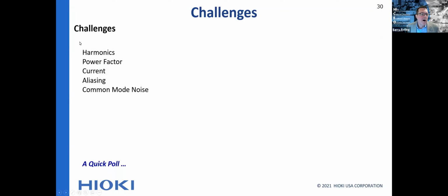So very quickly, I'll review my challenges, and then I'll hand the presentation over to Naomichi. I explained to you about measuring harmonics and why we need to do it to about 5 orders. For that, you need bandwidth, which means you need more sample rate as well. We talked about power factor. Now we'll tell you how we can fix that. We can correct that phase shift. That's a rare feature, and you can't ignore high power factor at harmonic power elements.